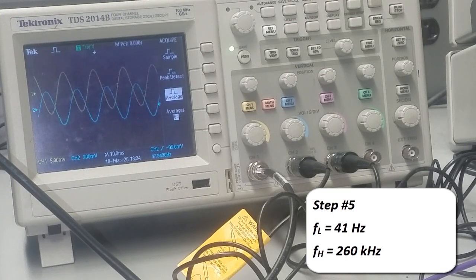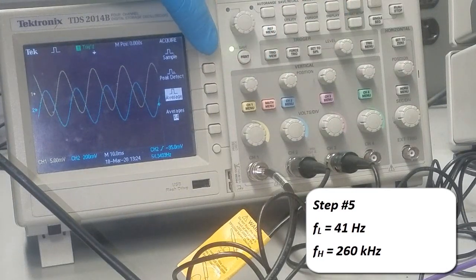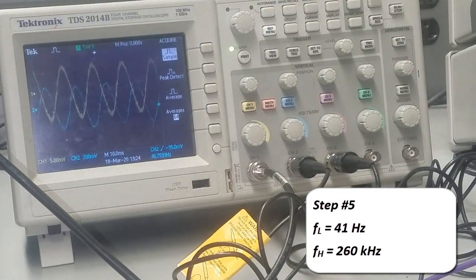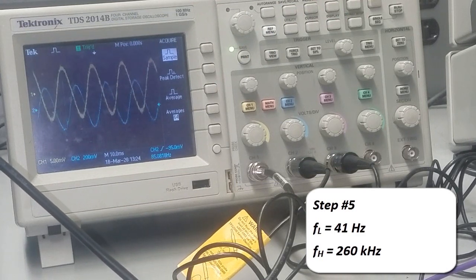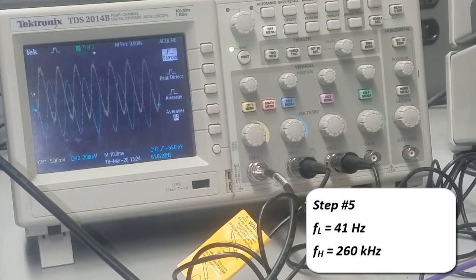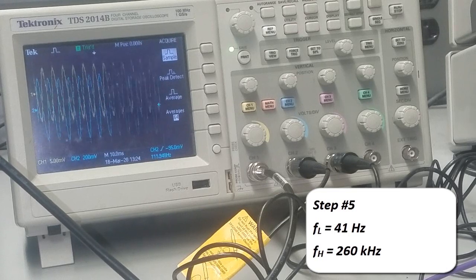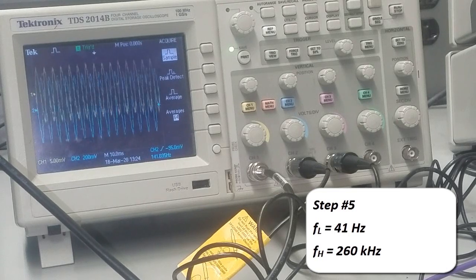So what I'm going to do here is acquire, and then sample. So you can see that the signal is noisy, and I will start to increase the frequency. You will start to see that the gain will increase. So I'm going to start increasing the frequency now on the function generator. This is at 50 kilohertz. You can see that it starts to shrink, and then the gain starts to increase. Here I'm at around 150 kilohertz.